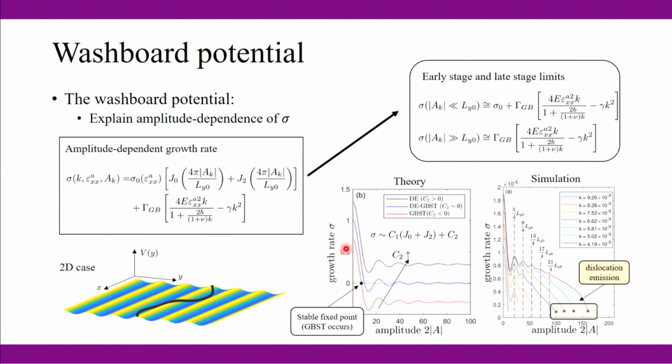Let's say this red line is positive, right? But as the amplitude grows, it is going to experience this coincident site lattice, so you're trying to climb. That's why you have these drops of the growth rate. But when it drops to 0, after that it will be something negative. When it hits 0, it should not grow anymore, so it becomes stuck. That explains why we see this kind of curvy profile, and locally you will see this grain boundary structure transformation.